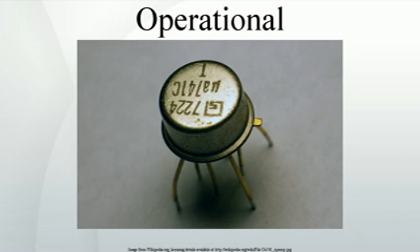None of these ideals can be perfectly realized. A real op-amp may be modeled with non-infinite or non-zero parameters using equivalent resistors and capacitors in the op-amp model. The designer can then include these effects into the overall performance of the final circuit. Some parameters may turn out to have negligible effect on the final design while others represent actual limitations of the final performance that must be evaluated.